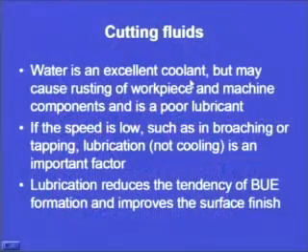So, water is an excellent coolant, but it may cause rusting of the workpiece and machine components, and it is a poor lubricant. Already I have told you we can directly choose water as a coolant, but it depends on whether we want lubrication also or not. If we do not want lubrication, we can directly use water as a coolant. But another limitation while using water as a coolant is that it may sometimes result in rusting. The rust may be on the workpiece as well as on the machine components, because in a machine tool the coolant or lubricant system is incorporated and has to be recycled again and again. So, water will be in direct contact with different machine elements. If proper care is not taken, water may result in rusting of certain machine elements, and sometimes of the workpiece also. So, we can use water as a coolant, but under certain limiting conditions.